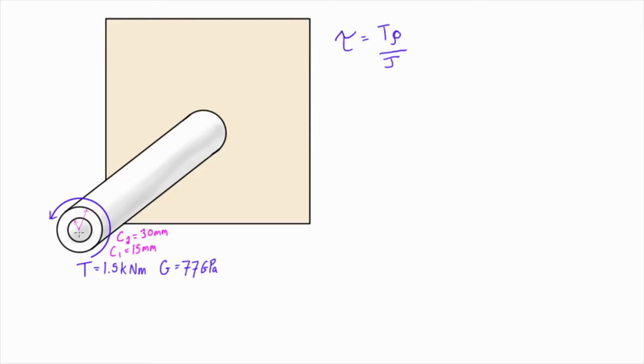And once you find the max shear, if you basically just extended it back down to the axis and set that to 0, you'd have a linear growth, just like we were having with the solid circular shafts, just where the minimum shear will be a non-zero value, but it'll be on that linear scale of increasing shear with increasing distance from the axis.